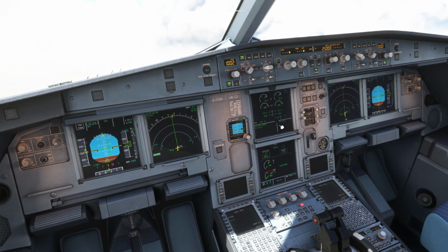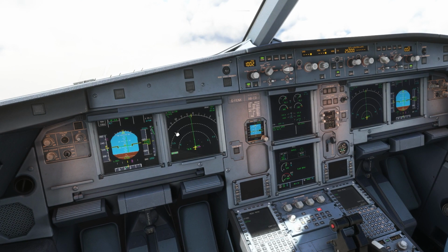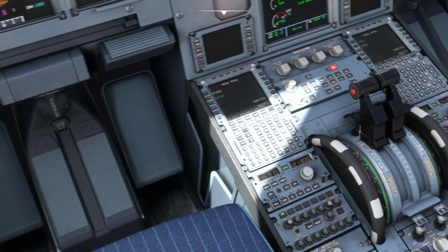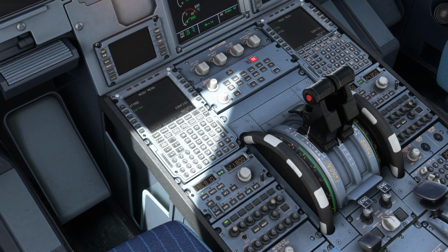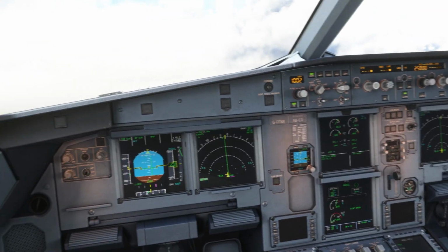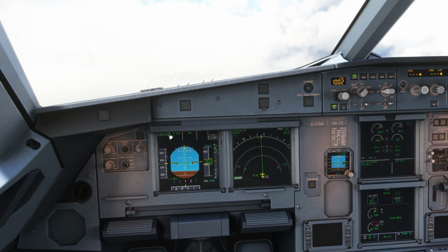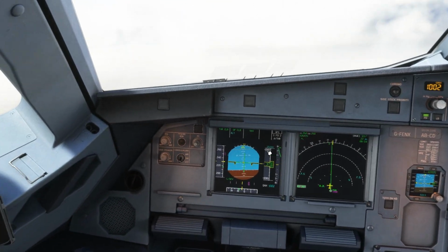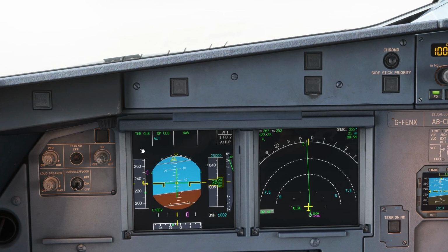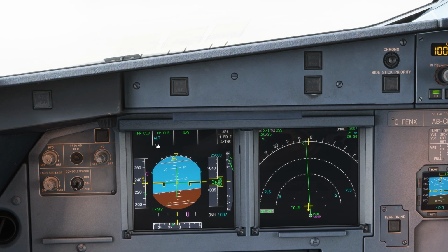So now the flaps are retracted, and now the lever climb has to be reduced. Right now it is set to TOGA, so I will just reduce the thrust to climb. As you can see over here, thrust climb is coming, and at this point I can turn on the autopilot. Now you can see it over here at the FMA, which is the flight mode annunciator.